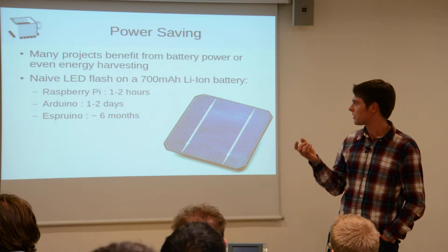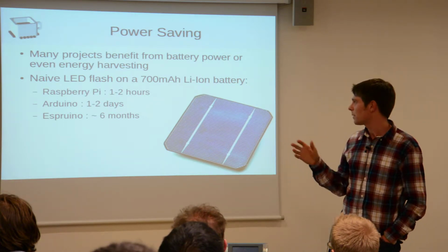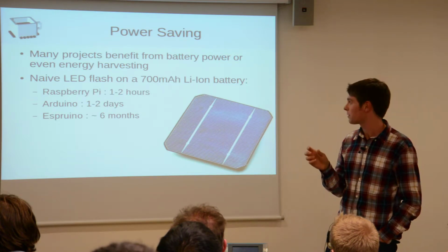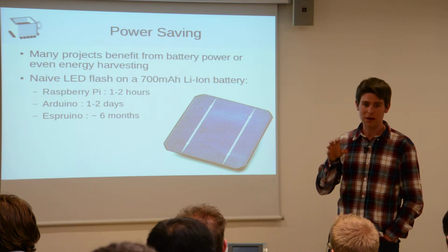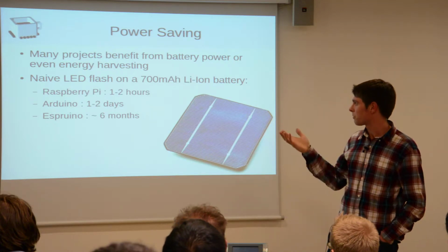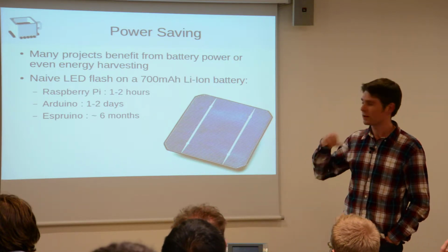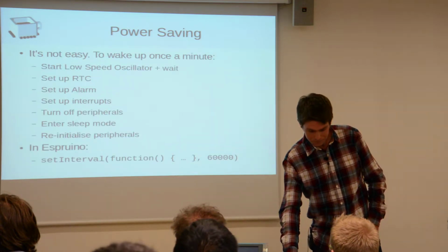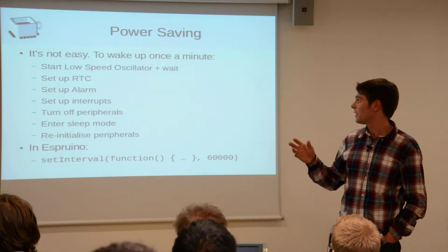So it seems crazy that an Arduino that's just one chip will probably only run for 1 or 2 days. Even the small ones are drawing about 20 milliamps, unless you put in special sleep code. The same with Raspberry Pi. The Espruino will manage to do it a lot better because it just knows it can sleep.